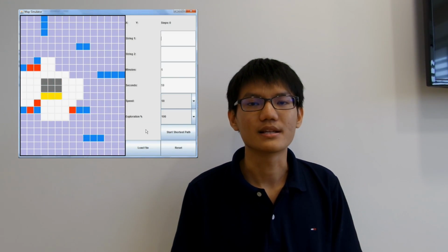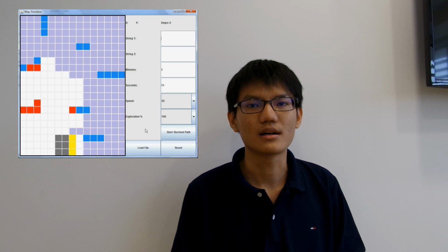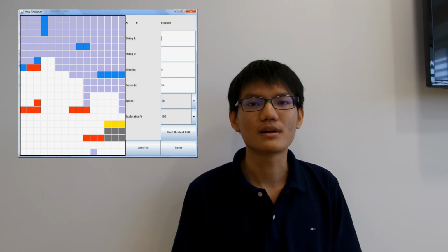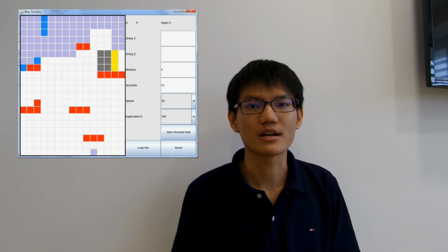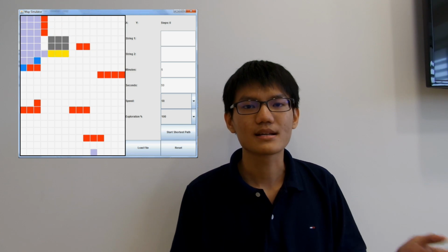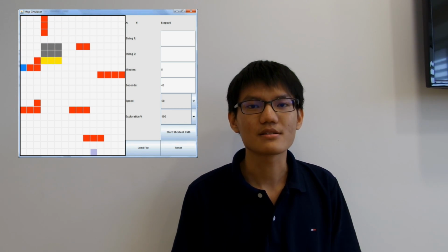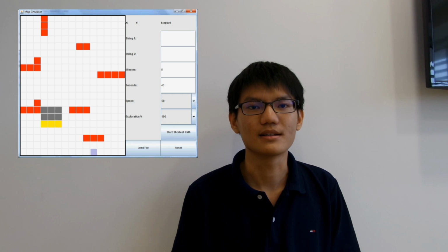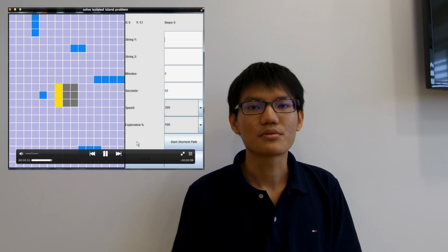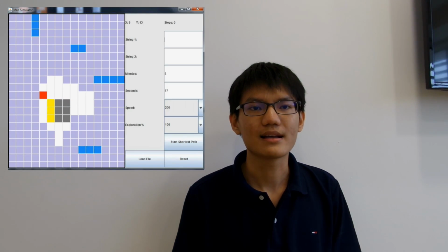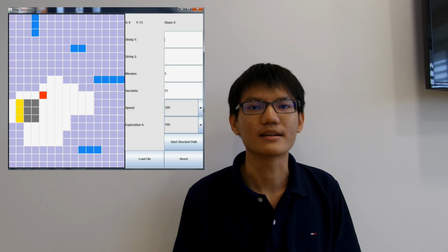For the exploration, we use the right wall follower with a flash algorithm, which sets the robot to move to the nearest wall. Then the robot will move around the arena in an anti-clockwise direction. The robot keeps obstacles on its right side and keeps track of all its turns using a counter. It will prevent the infinite loop problem due to the isolated island problem or incorrect sensor readings.